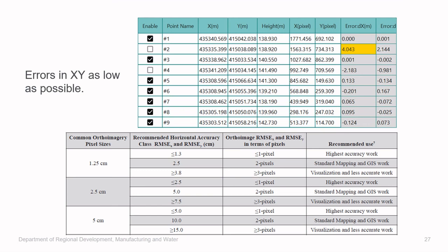The recommendation from this international standard is that after you finish the rectification, whatever your final scaling value is, the RMSE is a minimum of 2 times the pixel size, or an error of 2 pixels. That's a recommendation for standard mapping and GIS work, so precisely what we're doing with image velocimetry, using the pixels to measure distances.